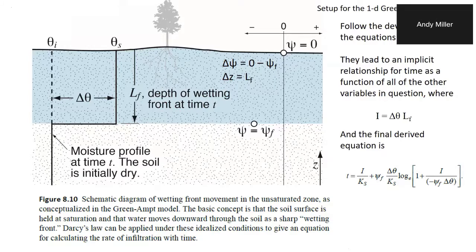So here's the interesting thing. Do you remember when we did the specific energy diagram and we developed the equations, and we started with a cubic equation, we had to basically do trial and error to find the water depth corresponding to a given value of specific energy, right? On both limbs of that curve. We couldn't solve for the depth from the specific energy. It was what we call an implicit equation. But what you could do is trial and error, keep putting in values of depth and seeing what specific energy they gave you. Then you could plot the depth against the specific energy and find what you needed to find.